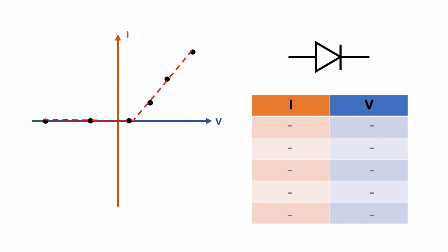An extra resistor can also be added in series to the circuit in order to keep the current low. This is to prevent damage to the diode. To measure this small current, a milliammeter may be preferable to a standard ammeter as it is more sensitive. And that brings us to the end of our required GCSE components.